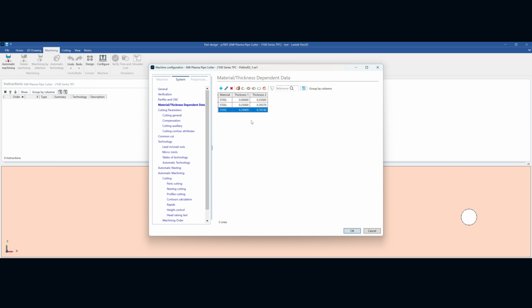If a rule is desired exclusively for the 1/2 inch range, you can add a new entry. Specify the range as just under and just over a 1/2 inch for thickness 1 and thickness 2, respectively. We will delete that for this demonstration. However, adding more definitions allows you to change how the part is cut, including compensation, lead-in, technology behavior, and end cuts for a specific material thickness. Navigating to Technology opens this window.